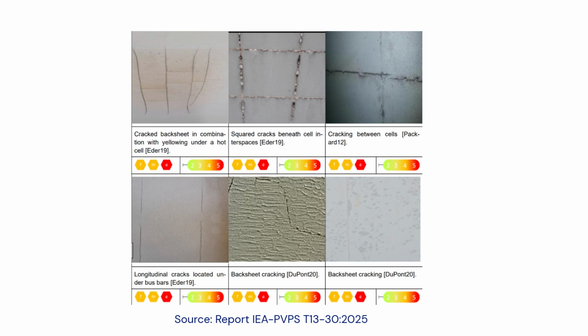The degradation of the backsheet can be caused by environmental factors like UV radiation, thermal stress, external mechanical stress, or by internal stress, like thermomechanical stress with the multimaterial composite PV module, or incorrect handling during transport and installation, local cuts, scratches. Deep backsheet cracking, whole backsheet stack split, is often followed by moisture ingress and corrosion. This is more frequent and severe under hot and humid conditions.